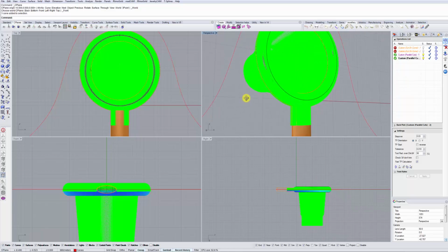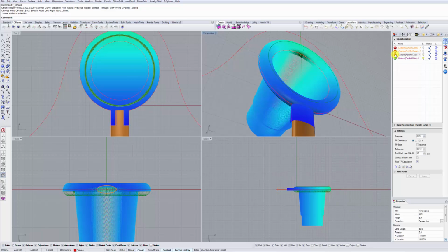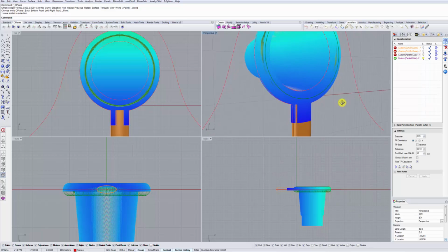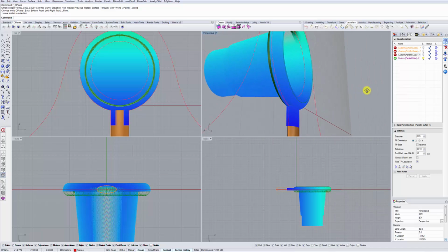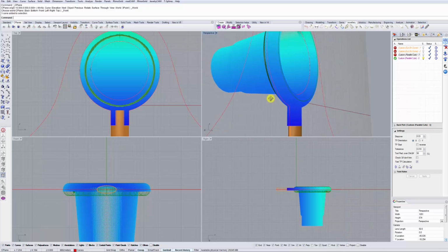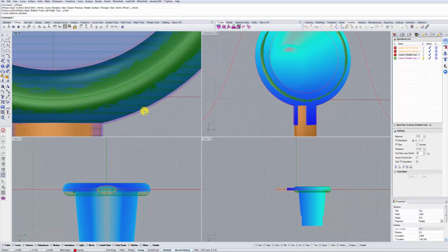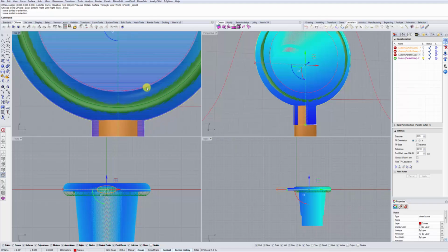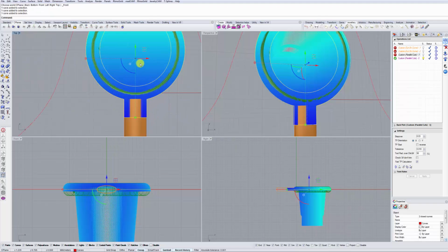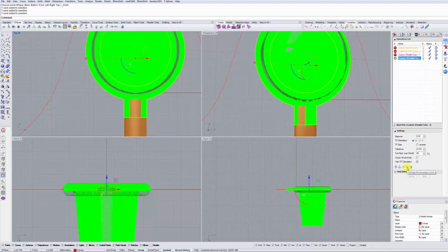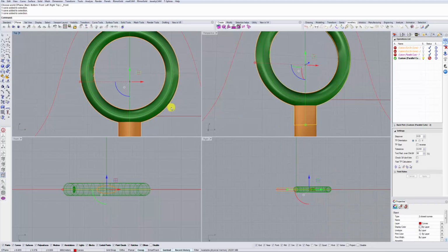So now, here's an interesting thing that happened. We have not specified any boundaries, any boundary surfaces, and it has waterfalled a ways down. The reason why this happened is because I only specified this outside boundary curve and not this inside curve. So we can correct that by going to our second operation, change boundary curve, selecting the two curves, and now recalculating a toolpath once again.